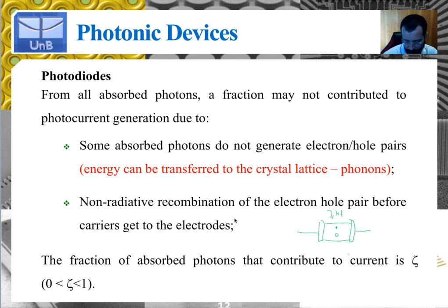And if you polarize the device in some way that we're going to look at later, this electron and hole can be put into motion, right? So if the electric field is to the right, the hole would move in the direction of the electric field and the electron would move in the opposite direction, and this would potentially constitute an electrical current right here.